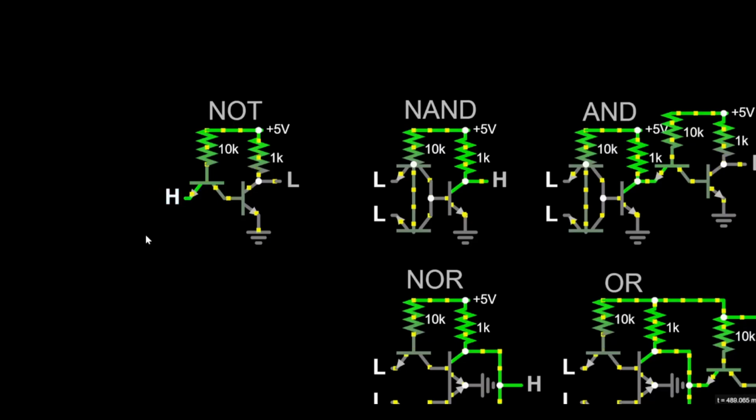So when you send a signal through the emitter, the signal still can flow through the collector and leak through into the base, but the majority of the current is flowing from the 5-volt line. Unlike the diode, which completely blocks the flow of current, some current can still leak through. That's pretty cool, I think, but not much different than the diode transistor logic. We've just made it so that we're using transistors instead of diodes.